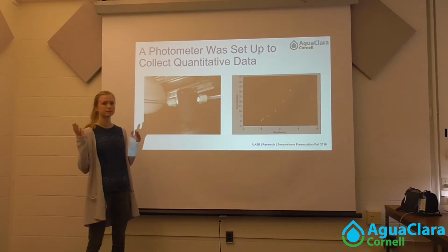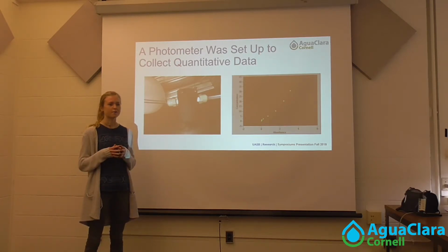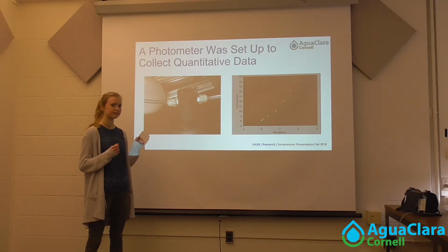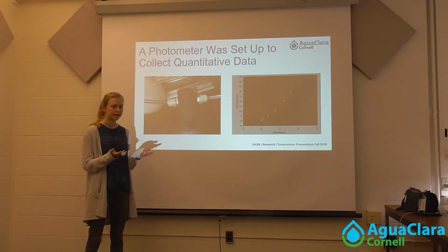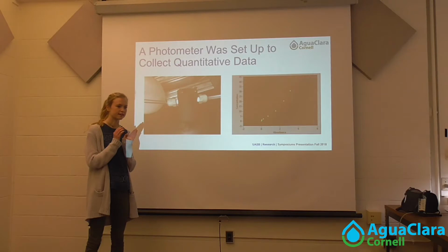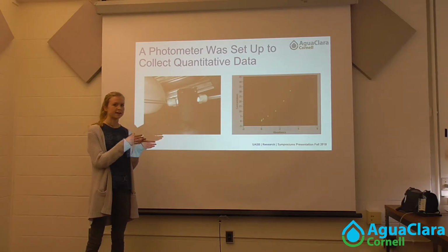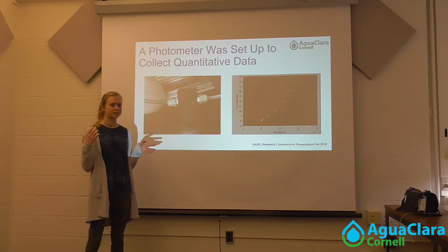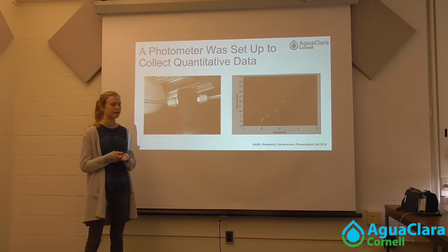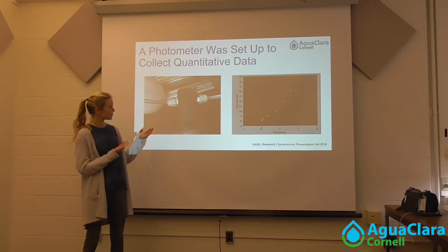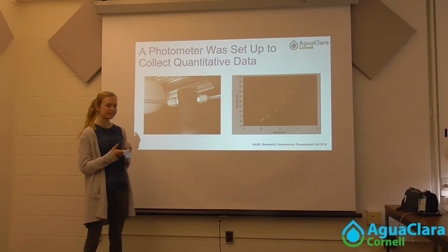As Kara was describing earlier, with our tapioca tests, we inject a plug of red dye into the reactor, and if the reactor is functioning properly, the red dye should flow up through the sludge blanket together in one burst, and then come out in the effluent line in a concentration similar to the concentration it was injected into the UASB reactor at. So there's our photometer, and that's generally what's going on with it.